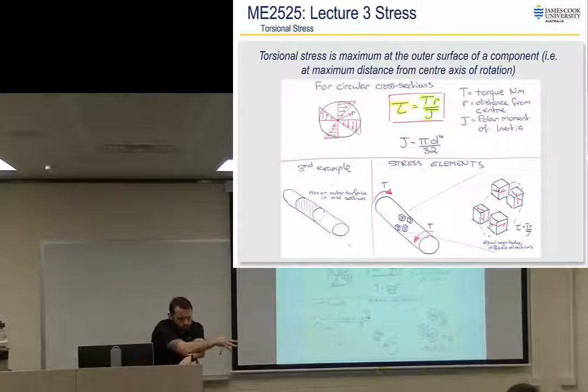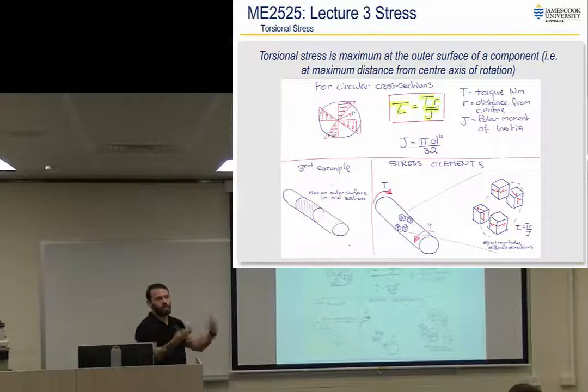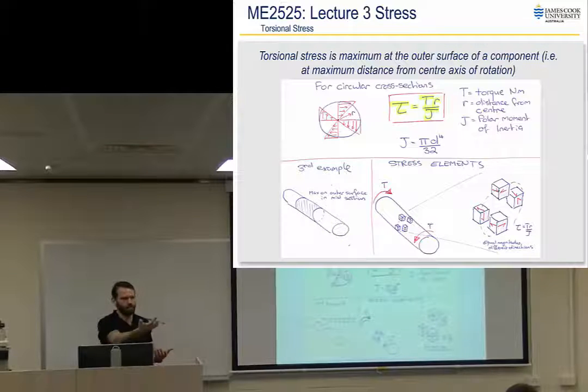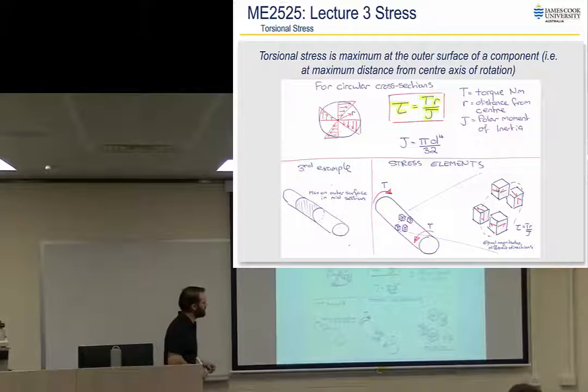So we did forces yesterday and before. The force caused stress, and funnily enough, the direction of force and the direction of stress happen in the same direction. So when we talk about shear stress, you have positive and negative on the shear force diagram. The shear stress will go in the same direction as that using your positive sign convention. I'll talk about that, but you can also get the same thing by doing the interpretation of what I just said. So that's why getting those positives and negatives right was so important. Because if you get them right, it agrees with the physics. If you get them wrong, it doesn't.